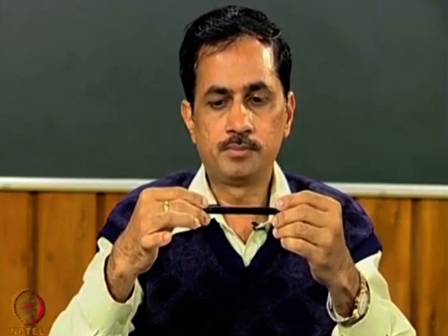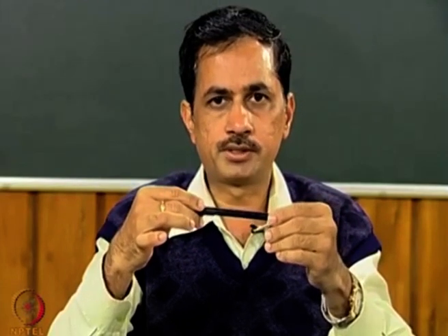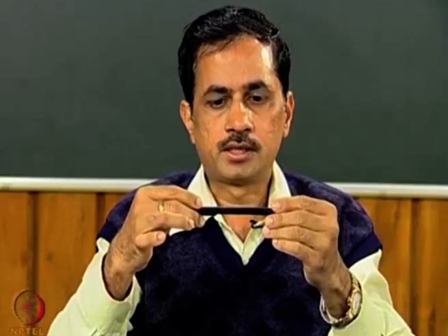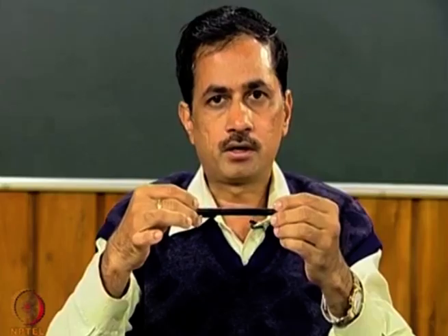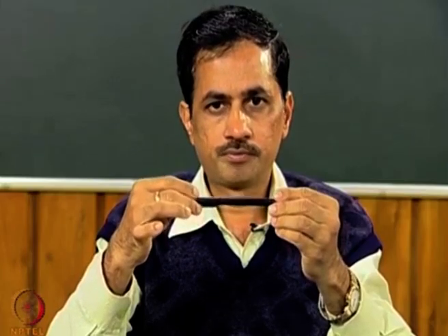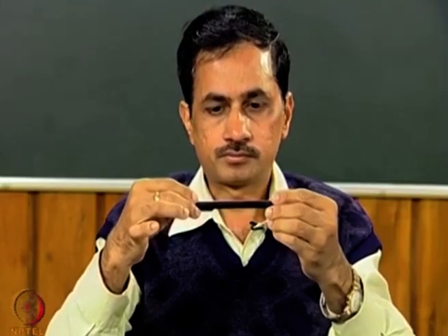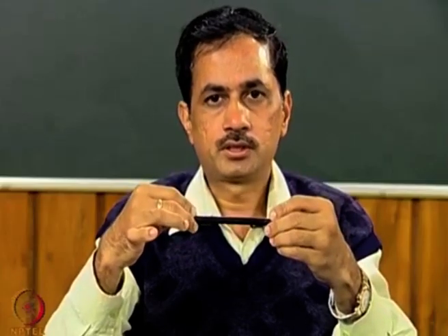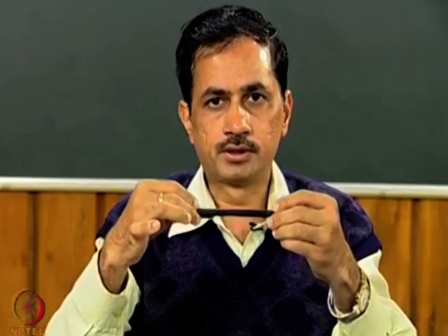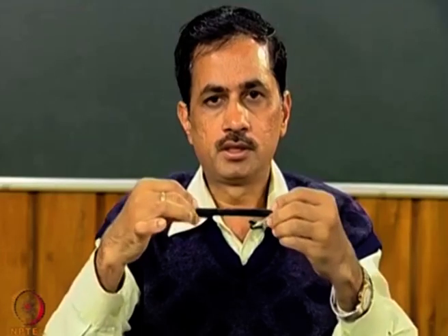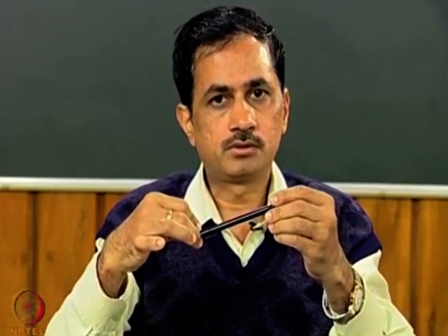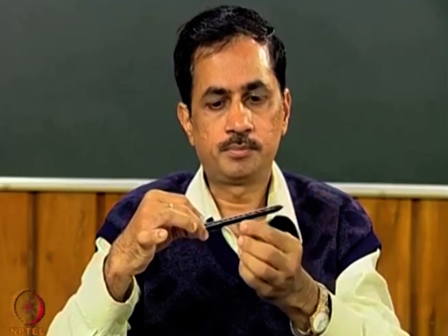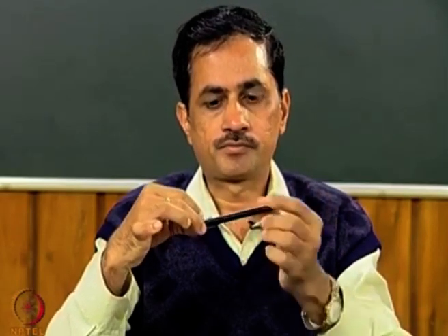So, as such, the bearing properties which we have considered at present are such that all the 4 degrees of freedom are uncoupled. That means, we can give this particular rotor the vertical translatory motion independent of other motion. Similarly, in the horizontal plane, and if we give a tilting, there is no translatory motion, only pure tilting is taking place.